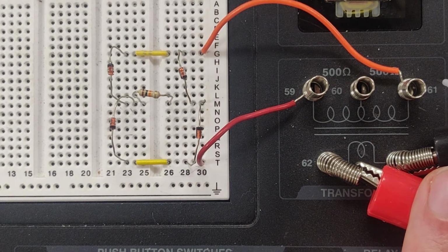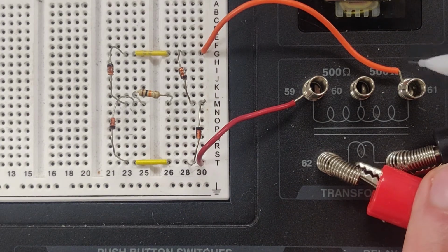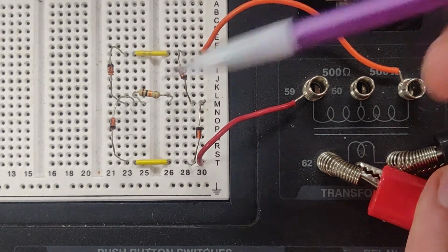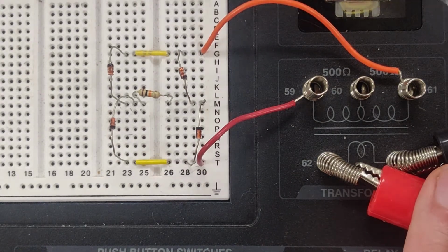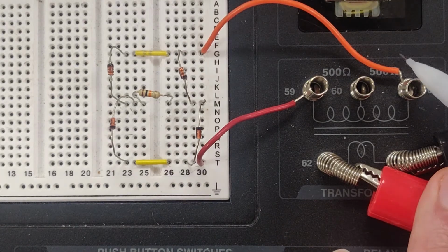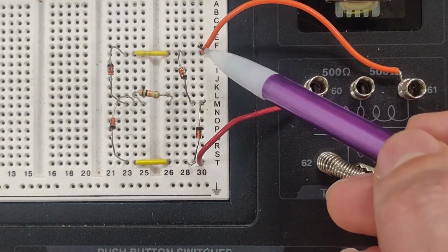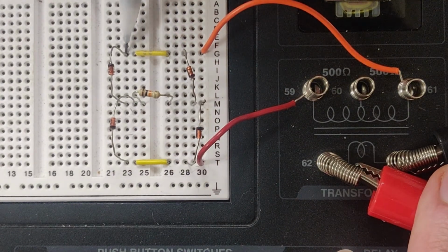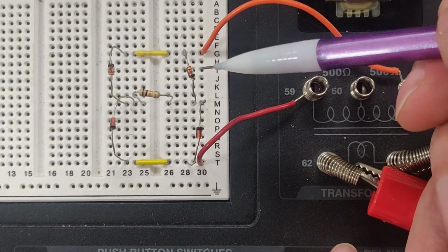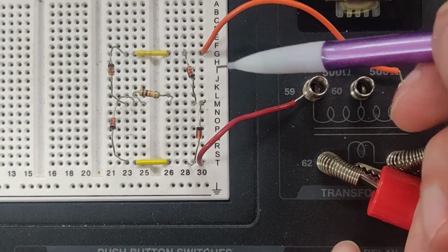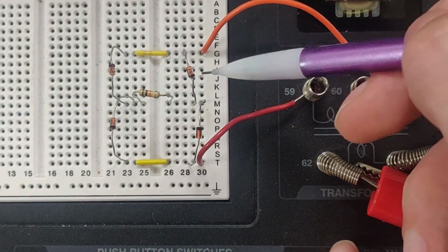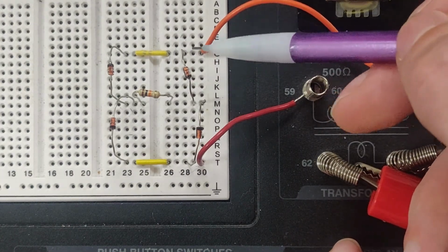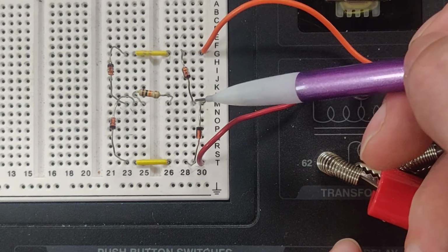So let me trace through the path of the current. This is still going to be an AC signal, so at one point the current's going to be going in this direction, and at the other point it's going to be going in the opposite direction. I'll talk about when the current is going this direction first. Current's flowing this way and it reaches this fork. It can either go over to this diode or down to this diode. Well, if the current is coming in this direction, this diode is in the reverse bias orientation and this one is in the forward bias orientation. You can see by the black line here and here. So current will go through here, down through this one, and it reaches this fork.